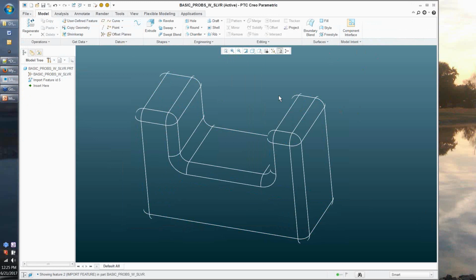If I attempt to increase the quality of the accuracy, which means a reduction in the number that is declared for part accuracy, the number of import problems will increase, and unfortunately, typically exponentially, because we're trying to build a piece of topology. PTC is trying to figure out where all those surface edges are to a greater accuracy than they were ever declared to begin with. And that's the context of you don't get back math you don't have.